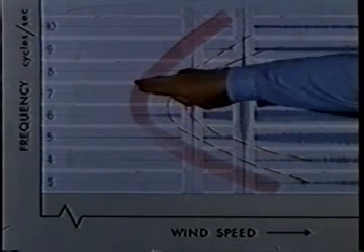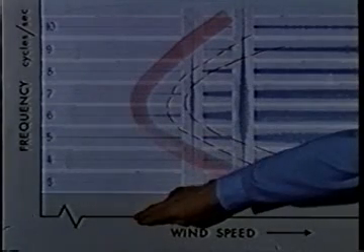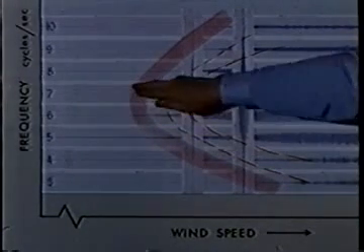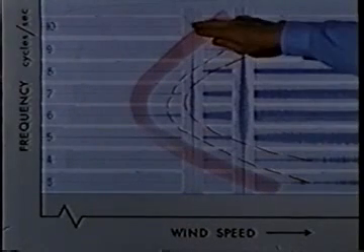Then accidental disturbances trigger the instability, and the first amplified waves will be in this frequency range at this wind speed, the critical wind speed. So we have seen that there is such a critical wind speed. We do have a selective amplifier, and the amplified frequency band does vary with wind speed.